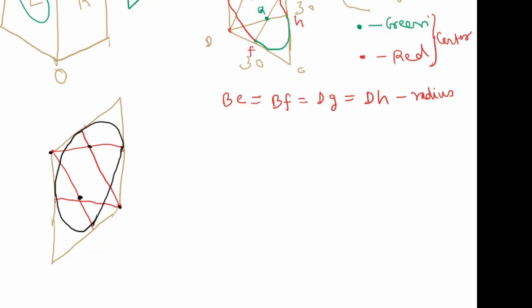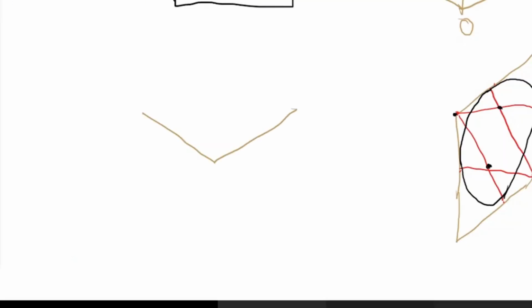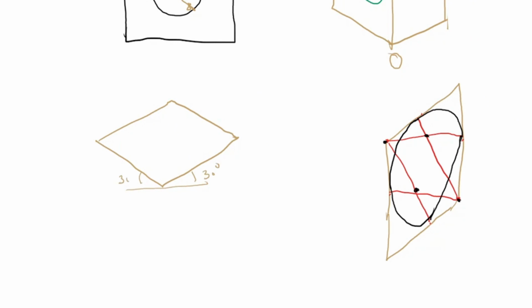And if you want to do it for the top surface, then what will it be? It will be parallel to the top surface. So parallel to this, so both of these will be 30 degree, 30 degree. Okay, this will be 30 degree, and this will also be 30 degree. Correct? Now how to draw this? Again, ignore the longer diagonal.